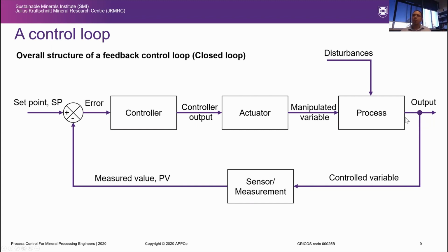And out of those outputs, there might be some that are of interest for controlling, and they call them control variables. There are some factors that affect your process performance which you might not have great control over, or you cannot change them. So we call them disturbances.